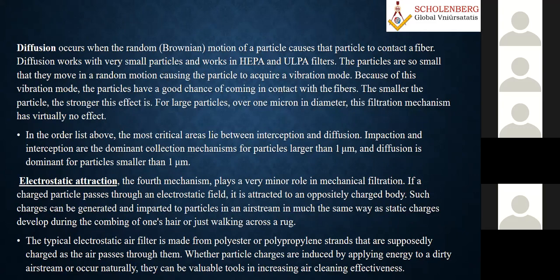Now, diffusion. This is basically Brownian movement. You must have seen it in physics, you must have studied Brownian motion. Basically, it is the motion of the particle that causes the particle to contact the fiber. It works with very small particles, even less than 10 micron. This may be 5 micron, it may come to 2 micron, or even less than 0.5 micron. So diffusion works with very small particles and works in HEPA filters. The particles are so small that they move in a random motion, Brownian motion, causing the particles to acquire a vibration mode.